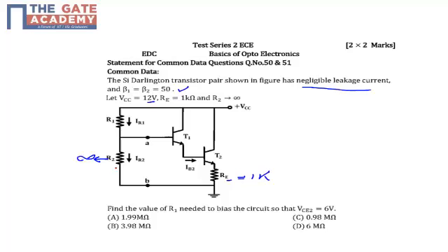So friends, what is the meaning of an infinite resistor? An infinite resistor will be equal to an open circuit. So if R2 is infinity, it means that my IR2 is 0, because this connection is electrically equivalent to an open circuit, no connection. In an open circuit the current is 0, so my IR2 must be equal to 0. So let's come to the first problem.